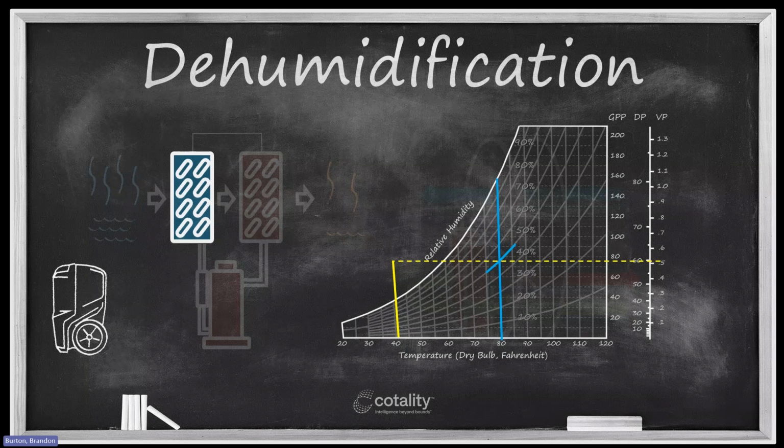That's a lot of cooling as that air passes through that refrigerant dehumidifier. All right, that takes a lot of energy to create that much cooling inside of that refrigeration system. And most refrigerant dehumidifiers are just not real good at doing that. You know, they'll give you a few degrees of cooling below dew point, but it's really hard when I've got to cool 40 degrees Fahrenheit and to get it all the way down to that temperature.